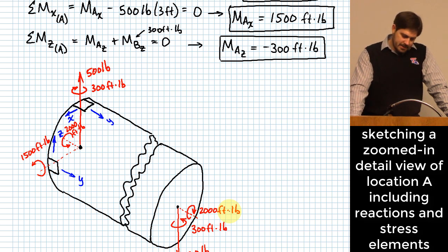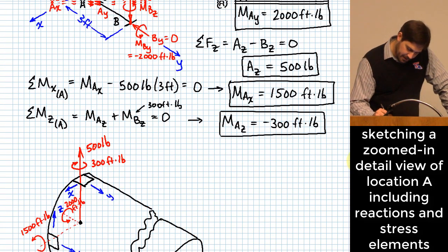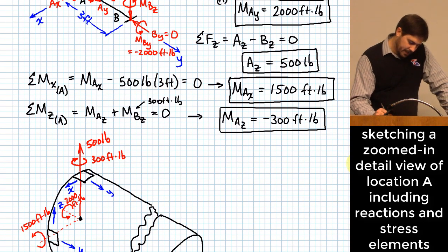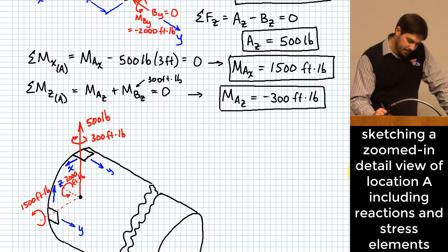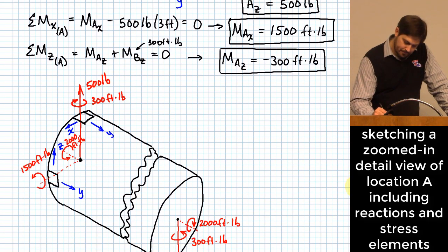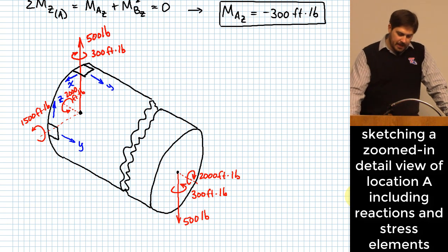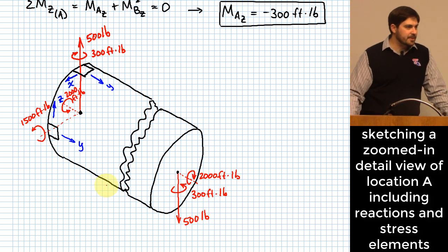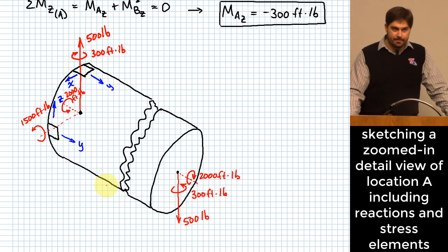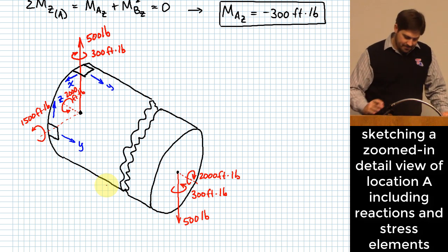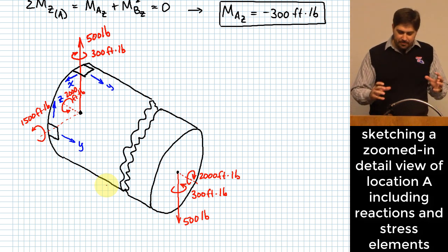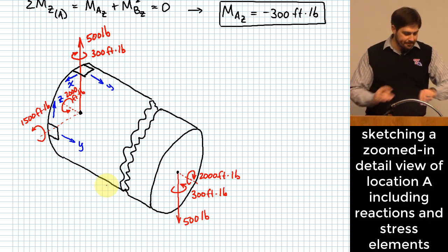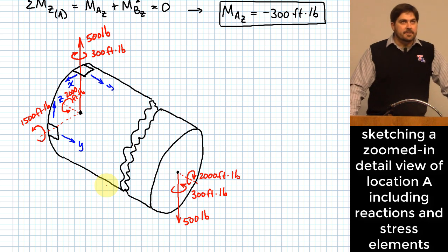All right, let's see. Is there anything else I need to think about there? Oh, MAX, at 1,500 foot-pounds, where did that come from? Okay, it came from my 500-pound force applied at 3 feet away from where the rod came out of the wall. All right, that sets up a whole bunch of good stuff, I think, in terms of being able to understand how these stresses get induced in the patches. What do you want to do next?